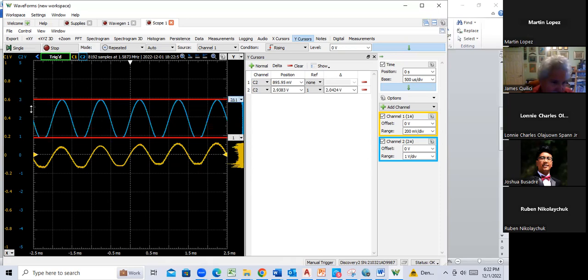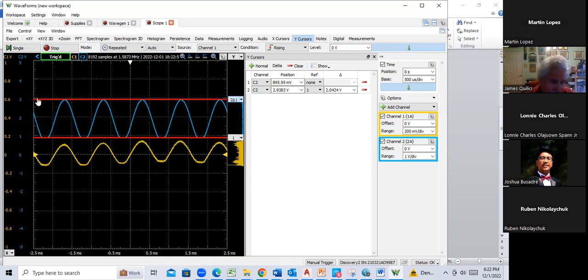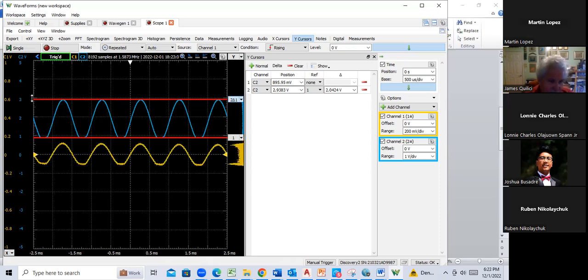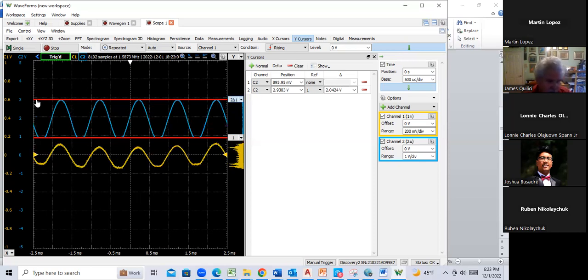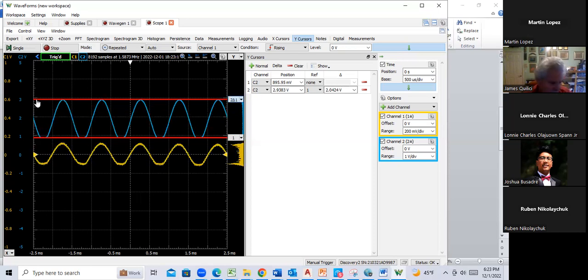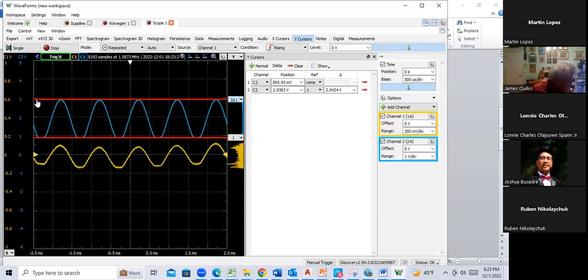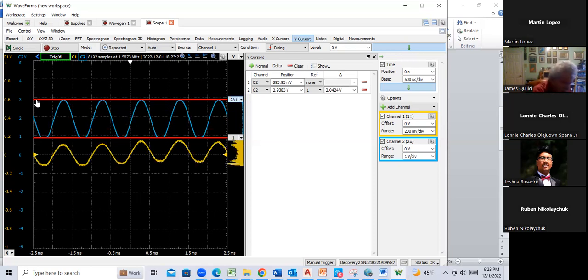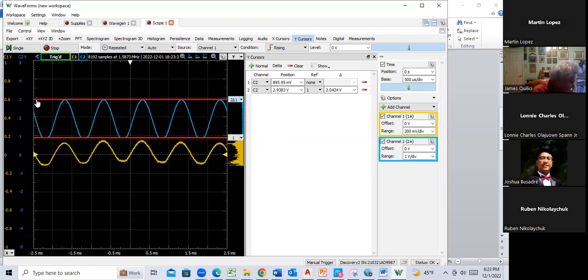Not ideal. Again, it would be better. I'd have to go through and recalculate. I think ideally I want the collector voltage sitting closer to 3. Maybe I can do that real quick. Hold on. Let's see. 1.26. I wanted 2 volts divided by 1.26 equals. Okay, I'm going to try to drop in a 1.5K. Yeah, 1.5K and see if that does it for me.